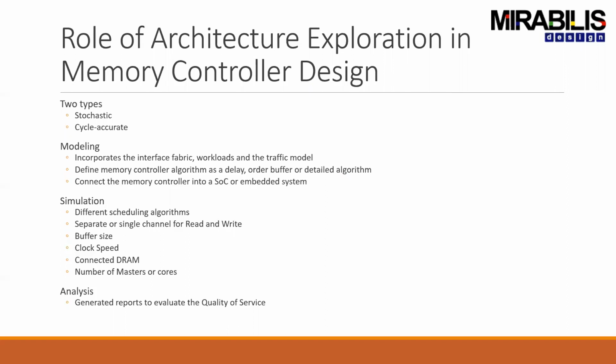Now, when you model, as I was showing you earlier, irrespective of whether it's stochastic or cycle accurate, you still need to worry about the interfaces, the workloads, the traffic, the software, all of those. And of course, the memory controller can be abstracted depending on stochastic or cycle accurate, but you still need to put in a sufficient amount of detail into either of those. Because the memory controller is the key aspect that you're trying to analyze and design.